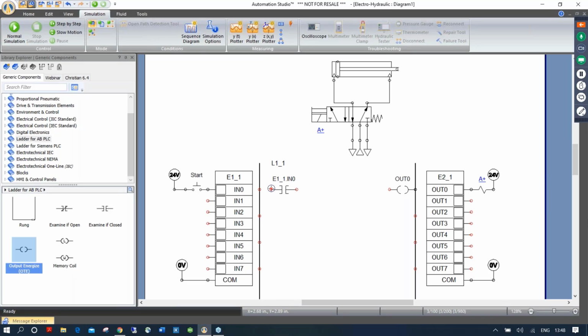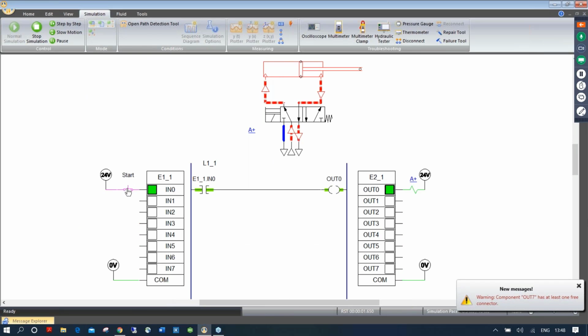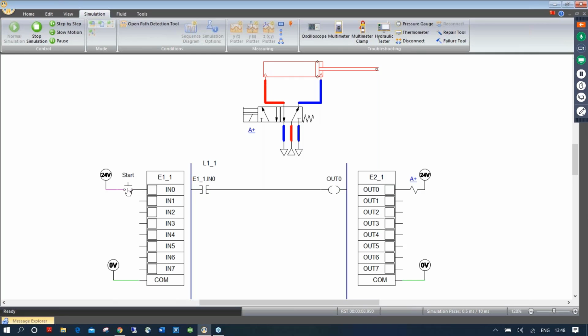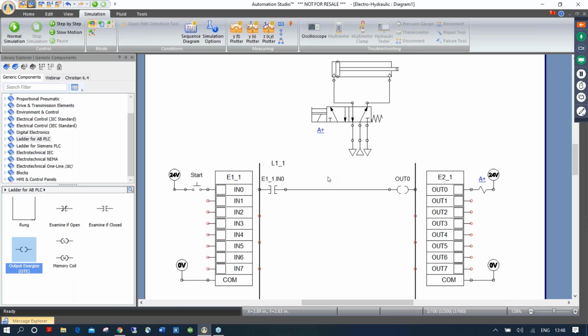So I'm going to connect these elements. I'm just going to bring this one like that on the side. Click this one here. And now if I start simulation, I have my circuit that works with the logic in the PLC. If you want to do a latch like we did before, I'm going to have to use an internal bit, internal relay, let's say. So I can actually hold the shift key down to disconnect this one because I want to put it a bit lower here.